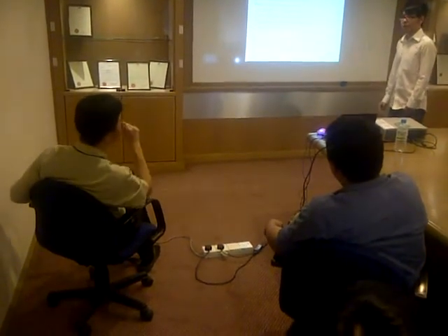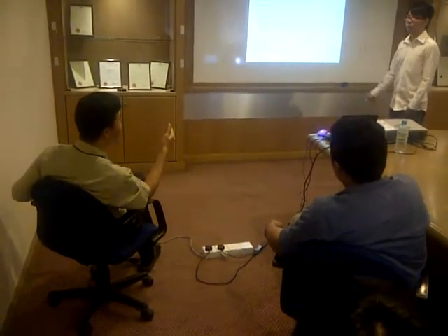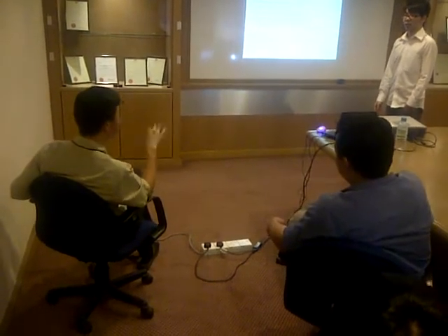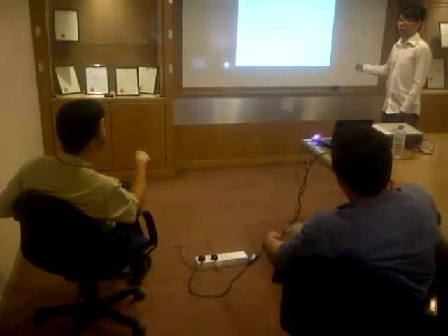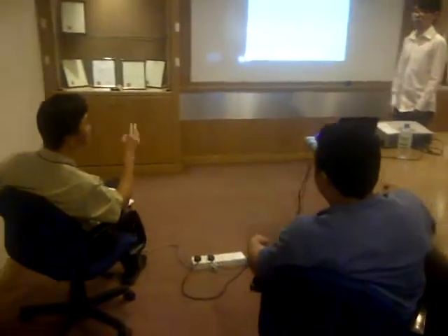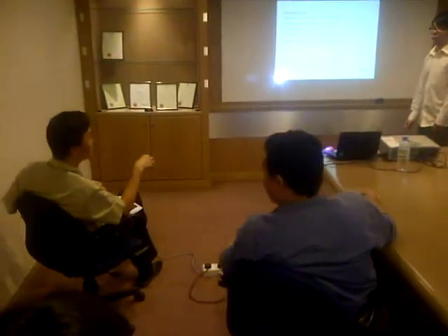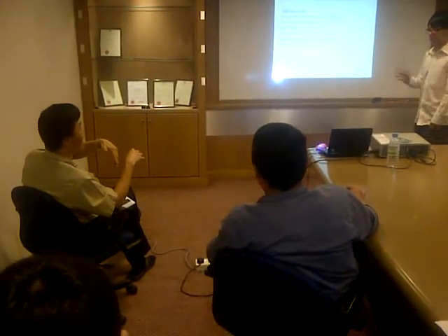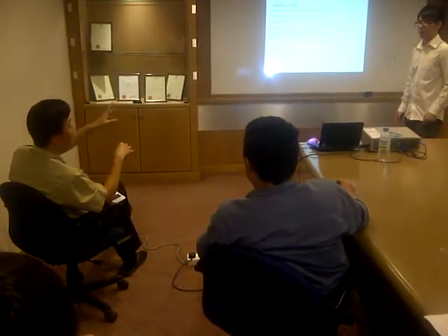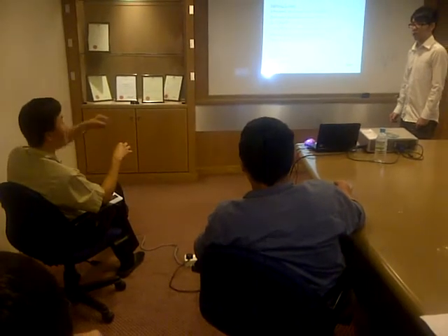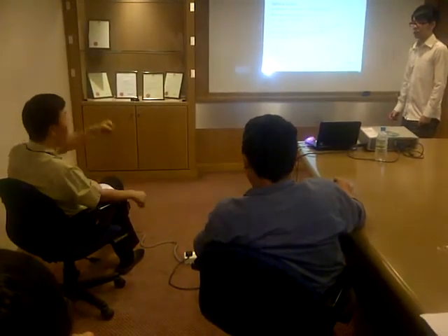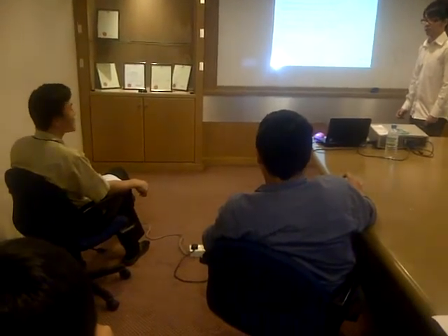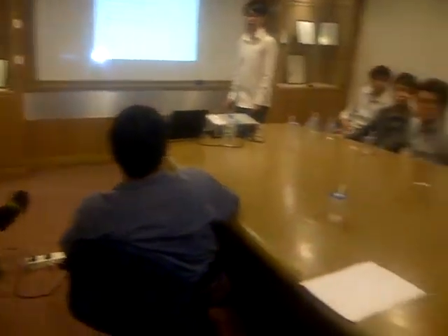That's the reason why just now I emphasized single core, 4 core. When you read the table, single core is a different reading, 4 core is a different reading. Copper is a different reading, aluminium is a different reading. Include the connection. Correct. When you connect in single phase, it's a different reading. When you connect in 3 phase, a different reading. So do you know how to read? Just not very familiar. Okay, never mind. Next time I can guide you, but you need to know how to read in order to get the right data, or else you plug in the wrong data, and wrong input equals wrong output. So your design won't be right. Do you teach them how to read data, Roy?